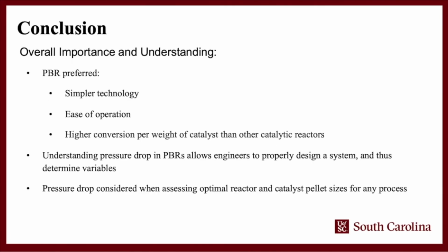Finally, our last slide. So for the overall importance and understanding of why we use PBRs and why we account for a pressure drop, first, we prefer PBRs because it's a simpler technology, it's easy to operate, and it gives us a higher conversion per weight of catalyst compared to other catalytic reactors.